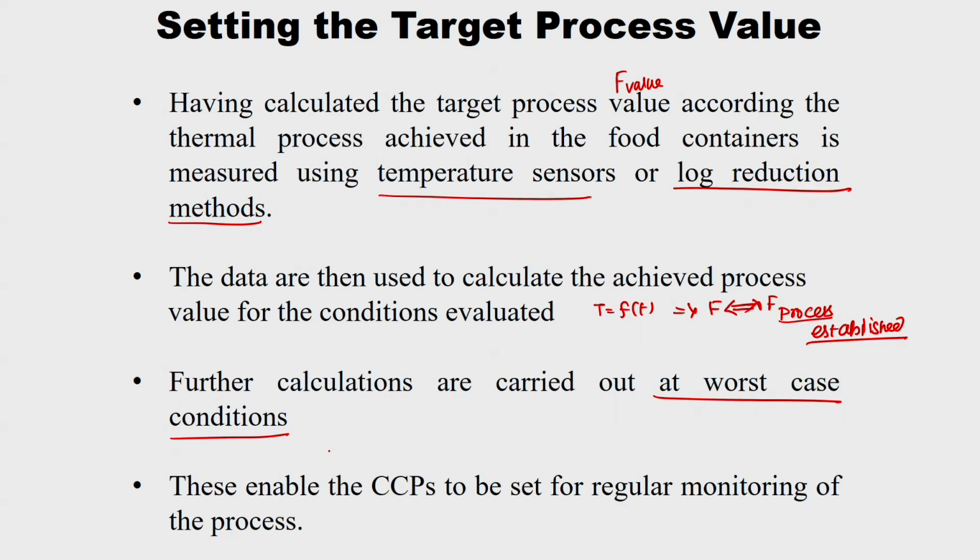And also while selecting worst conditions, care should be taken. One worst condition, for example, for pasteurization: I am employing my food product at a normal atmospheric temperature of 35, right, and it is heated to 63 for 30 minutes, right. But if I employ my product at 30 degrees, less than the normally employed inlet temperature, then your F value may be higher, right, because this T is also taken care of while processing.